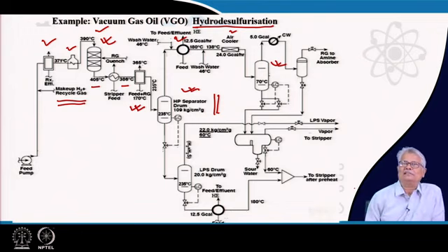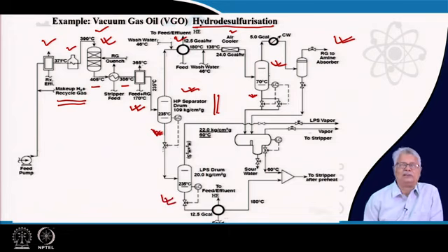The sulfur which gets removed forms hydrogen sulfide, and finally it goes here for recovery of H2S from that off gas. The liquid is always coming from the bottom of these. So, this is also a bottom arrangement, and it goes to a low pressure separator drum, which is again a flash. Here the flashing happens at 20 kg, whereas the upper drum or the high pressure drum, it happens at 109 kg pressure.